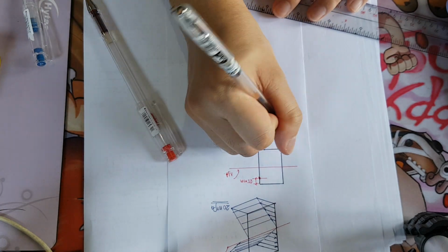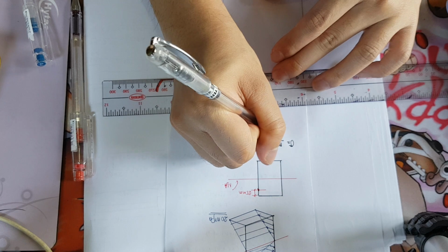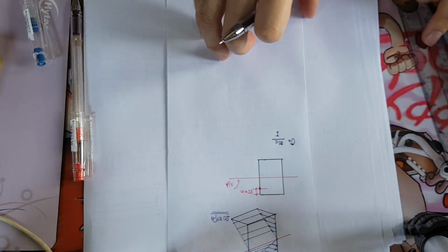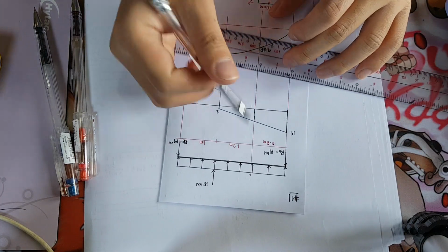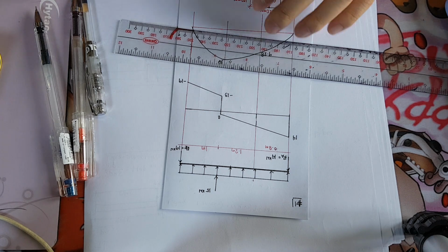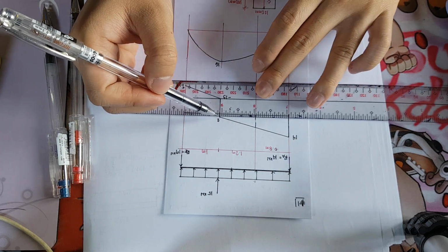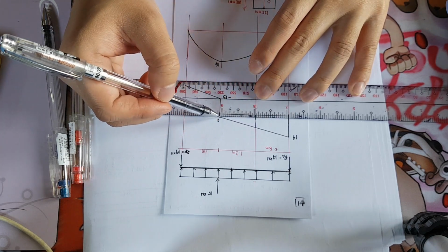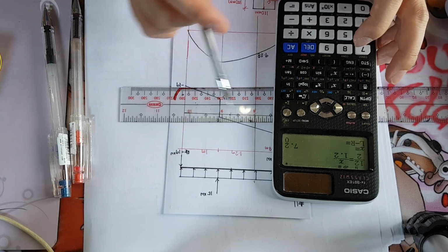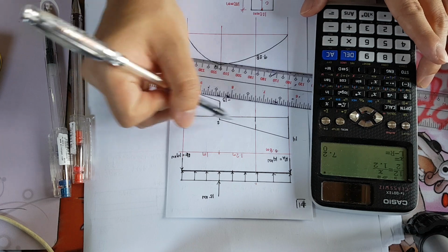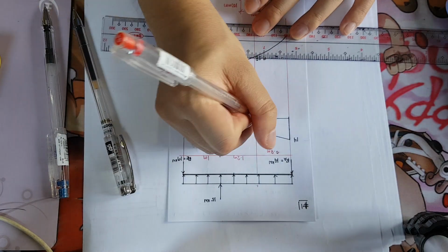Take note that our working equation is equivalent to Mc over I. And yung hinahanap nating moment is you have 0.8 meters from a support. So by similar triangle, we have 14 minus 2, that is 12. 12 is to the distance of 2 meters, while 1.2 is to the height of alpha x. And that is 7.2. But do not forget that we have an additional of 2 because this is a trapezoidal load. Therefore, that is equivalent to 9.2. So the height here or the shear here is 9.2.